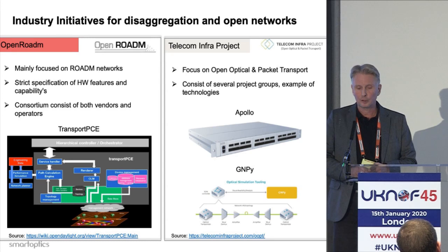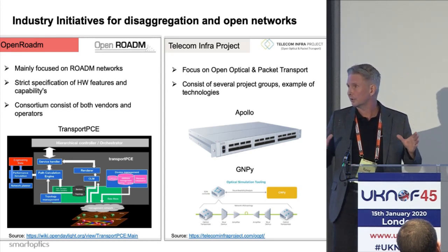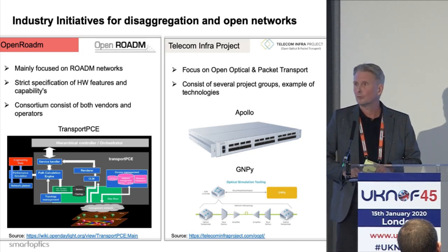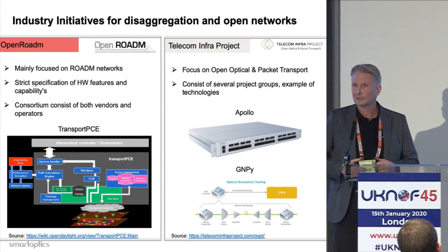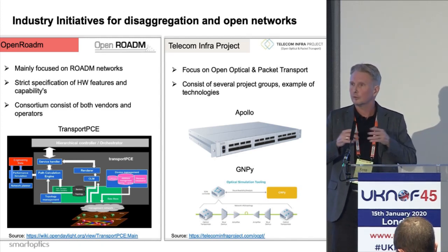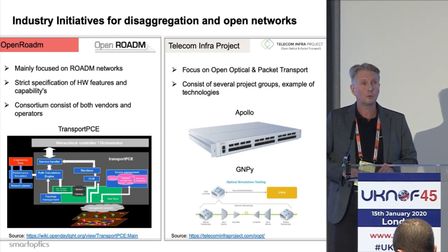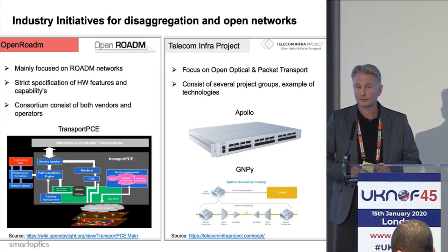And then you have the topology manager. The topology manager builds up the topology of the network by using LLDP, and from there builds a network topology showing what the network looks like. You have a renderer in there that is handling the optical component setting, so it configures the optical network, the route through the network, and so on. And then, last but not least, you have the OLM. The OLM is controlling in real time your optical power level, doing all the power balancing and so on in the network. So those are the different modules within TransportPCE.